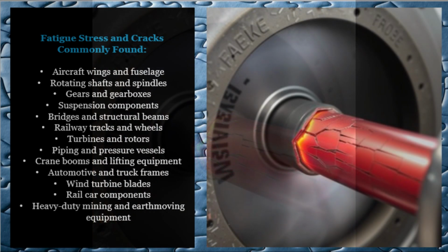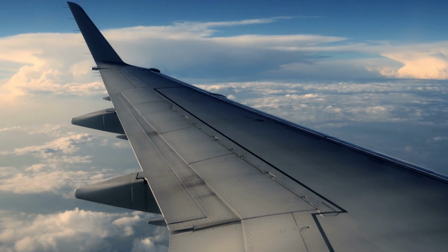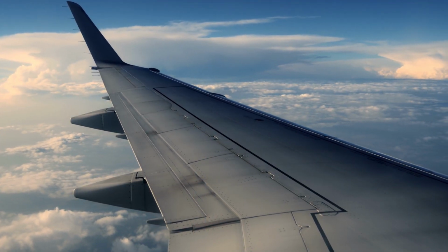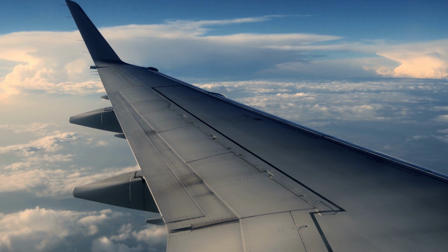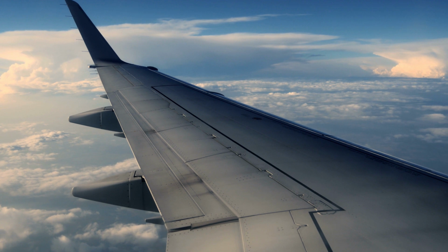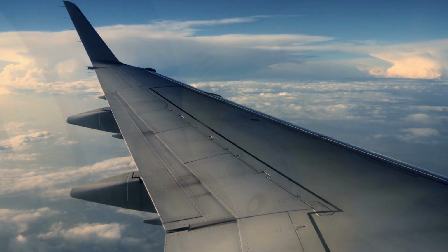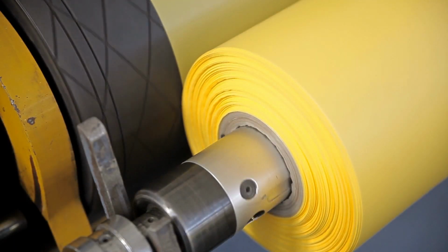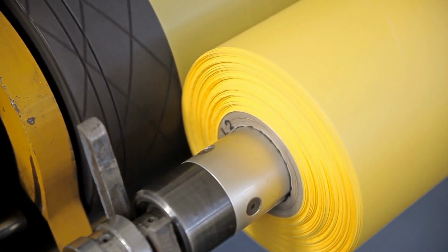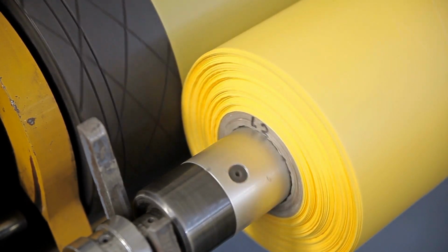Common in equipment. Fatigue stress is particularly common in equipment that undergoes repeated cycles of stress, such as aircraft wings, rotating shafts, gears, and suspension components. In aircraft, wings flex repeatedly due to varying aerodynamic forces, making them prone to fatigue stress over time. Rotating shafts in engines, gearboxes, and drive trains experience constant cycles of tension and compression, which can lead to fatigue cracks.